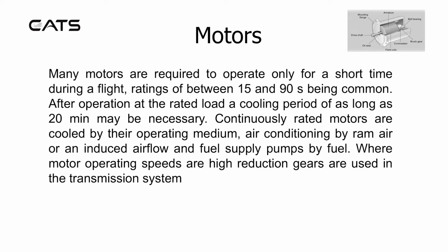Many motors are required to operate only for a short time during a flight, with ratings of between 15 and 90 seconds being common. After operation at the rated load, a cooling period of as long as 20 minutes may be necessary. Continuously rated motors are cooled by their operating medium: air conditioning by ram air or an induced airflow, and fuel supply pumps by fuel. Where motor operating speeds are high, reduction gears are used in the transmission system.